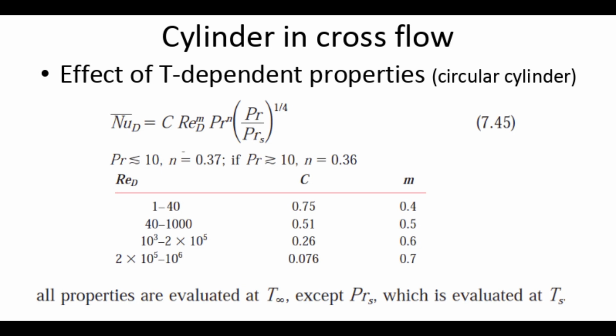Now, here's the interesting point of this. For some fluids, especially oil, the viscosity changes very much with temperature. So the Prandtl number changes very much with temperature. So what Prandtl number are you supposed to use? The one on the surface, the one in the fluid, right? If nobody tells you anything, you take the average between those two. That's called the film temperature. You take the average of surface and fluid, and you go with that. Perfect? No. But it's a good lie, right?